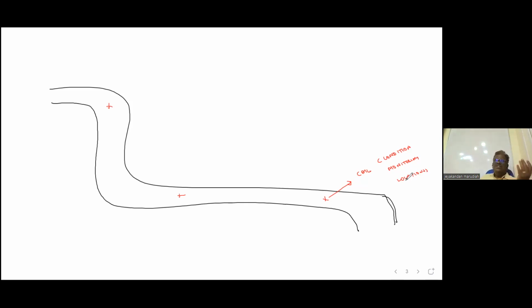It is like our CV. Every year we are revising our biodata based on our experience. Same way, it is how CML works. So the CML will have examination points. Now, if you take a circuit, I told you what is common: same material, same damage mechanism, same design condition. But even within a circuit, some portions can corrode differently. This can have an accelerated corrosion rate.